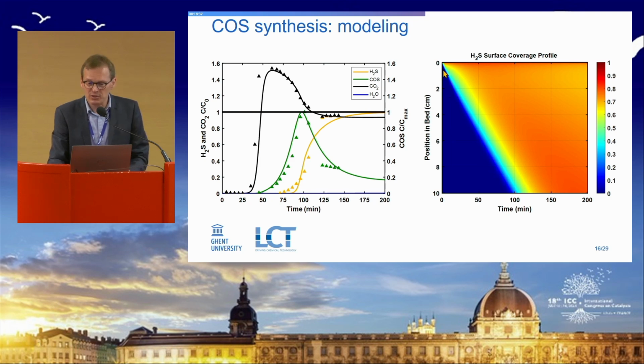So you see at the start of the reaction, the bed is completely empty. There is no H2S adsorbed yet. And as time progresses, you see how the hydrogen sulfide is getting through the bed and is adsorbing more and more.